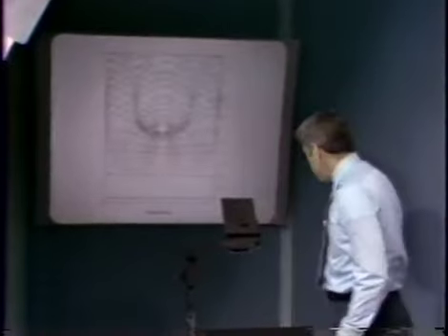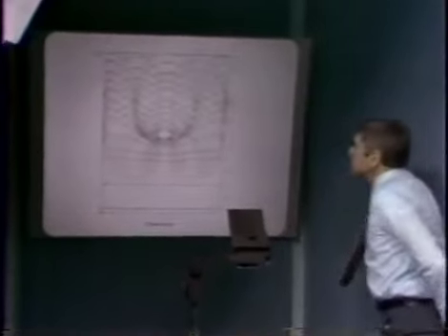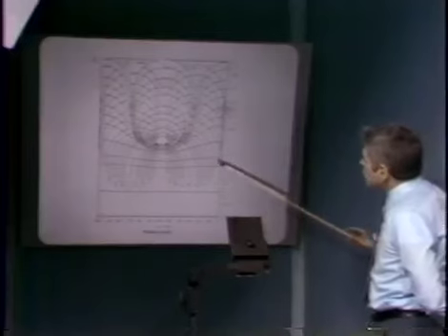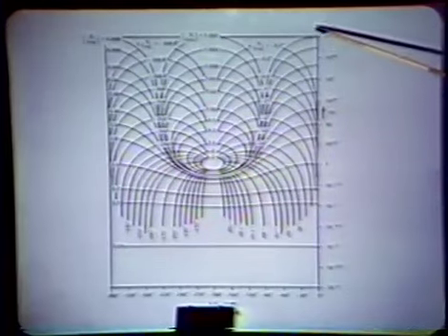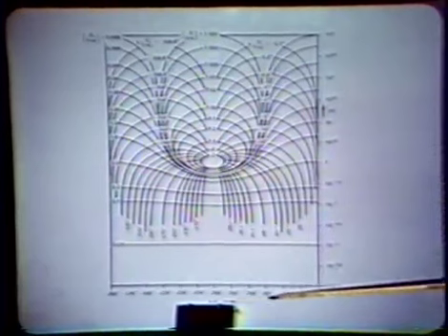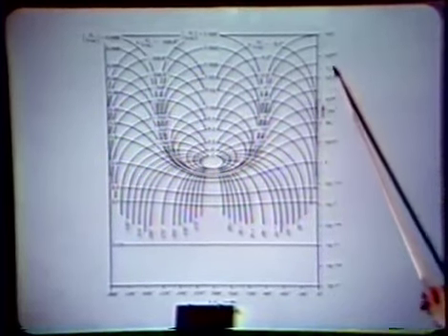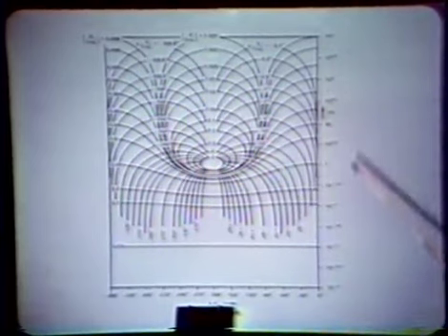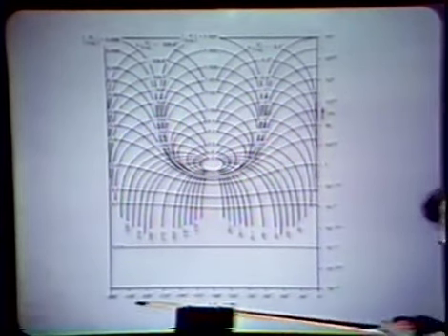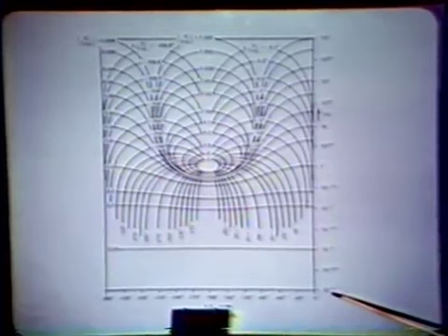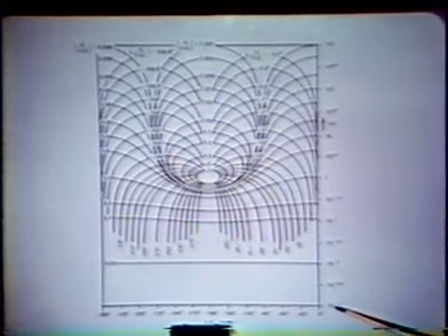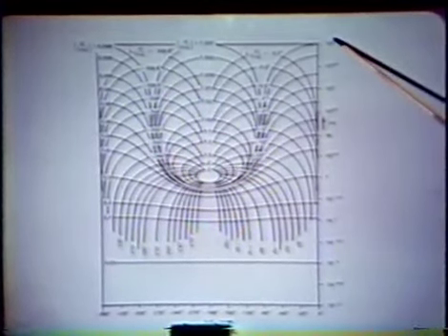And here's a Nichols Chart. It's a little bit confusing, but there is a grid in the background which are gain phase coordinates. Here's the magnitude of G, the angle of G along here. Here we have a magnitude of G running from 10 to the minus third up to 10 to the third.